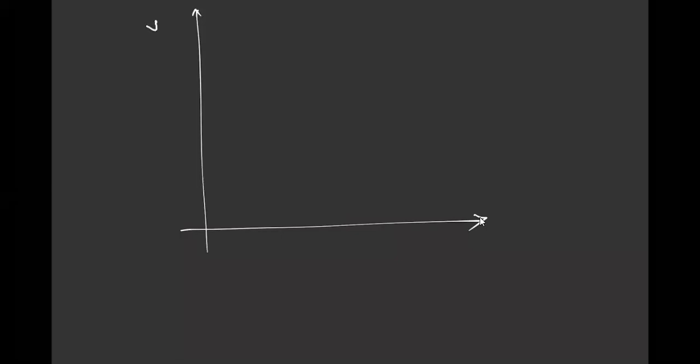So this is true values. Okay, as you see, I changed the curves. So my true values will always go up continuously. Why? Because if you see the math, you will be getting this. Somewhere you'll be getting a yield point, here you'll be getting the maximum, that is UTS.